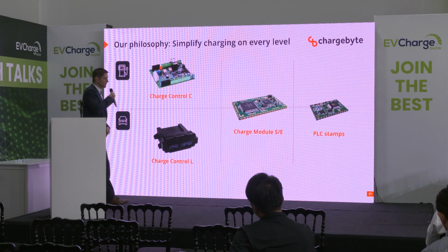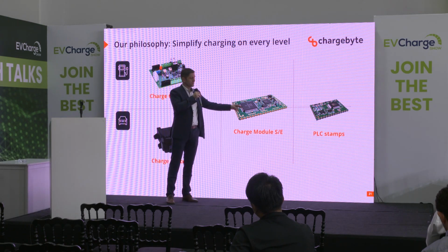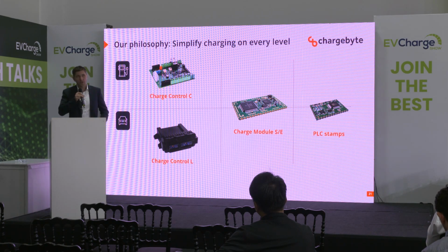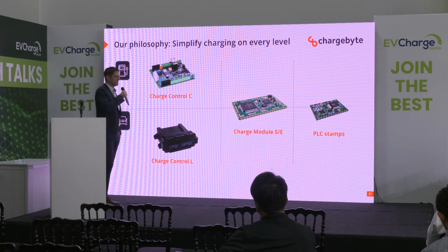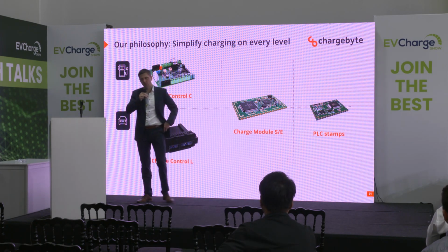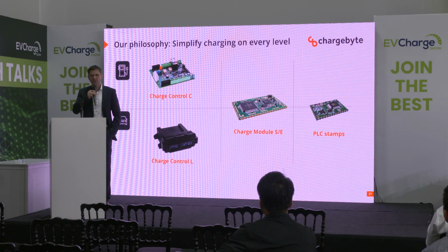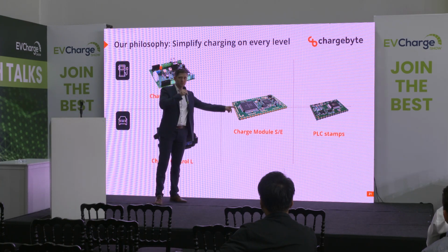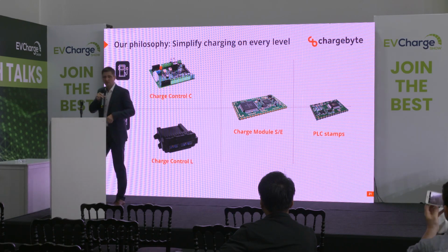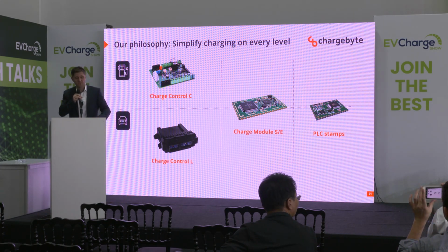Actually, what we did is we take these modules, which are pretty popular in the meantime, and we are adding a bit more features in it. So we are adding here an ESP32, which is a cheaper chip, but also has more processing power. And we are doing then here also OCPP, and have then a complete charge controller that you can just integrate. This is called a charge core. And we're doing here the same, but just with a Linux core, an IMX93, so that you can just integrate that and place your own stuff on that.